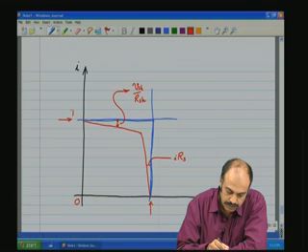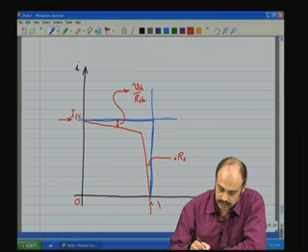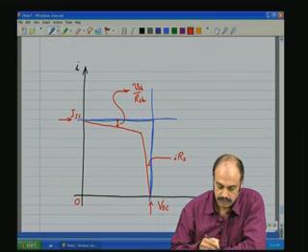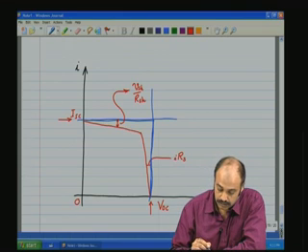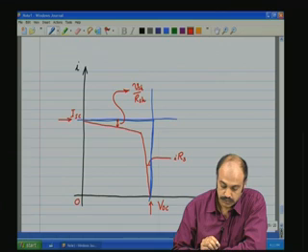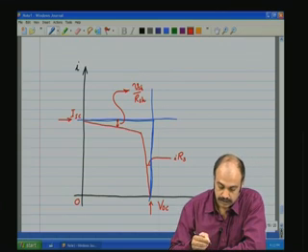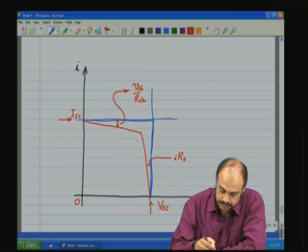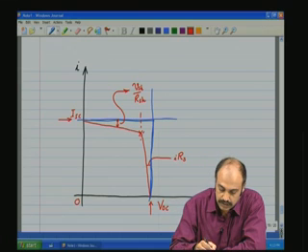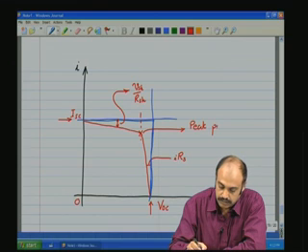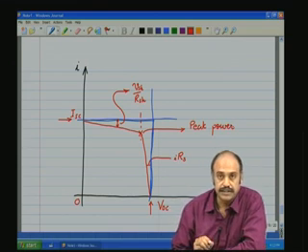This is called the short circuit current ISC point, and this is called open circuit voltage VOC point. In fact, these two parameters of the solar cell are data sheet parameters which you may have to check when you want to choose the solar cell for design. Another point that is of interest also is an operating point around here, around the knee, which will give you the peak power. Peak power. This also is a data sheet point.